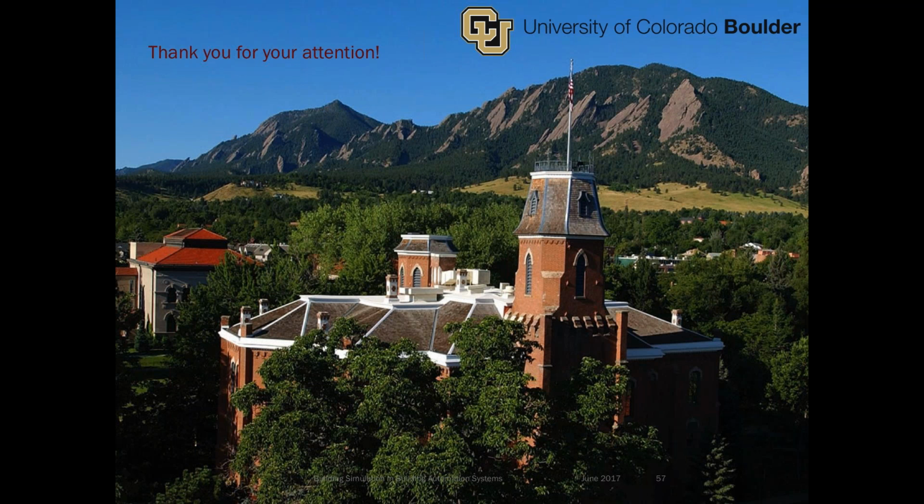And by training these models on training data and testing them on validation data, you can compare the model complexity against each other. And there's actually a metric that you can use, the generalized cross-validation index, GCV, that would tell you, under these circumstances for this building, the lighter model, the 8-parameter model, is actually better than the 21-parameter model.